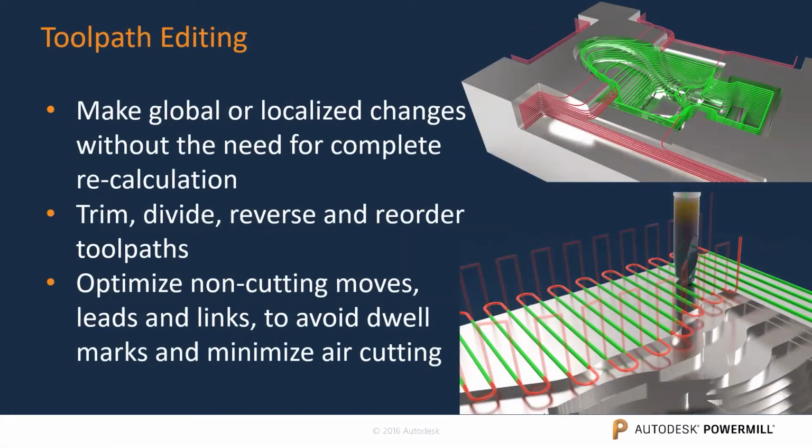And we also have the ability to go back after the toolpath is generated, instead of having to go in there and tweak every little detail to what we need, which there's cases where that's going to be necessary, but we also have the ability to, if we see something we don't like, go in there and edit that toolpath directly, like removing certain lines that are extra that we didn't need, or changing a linking. All that is calculated independently of the actual toolpath.